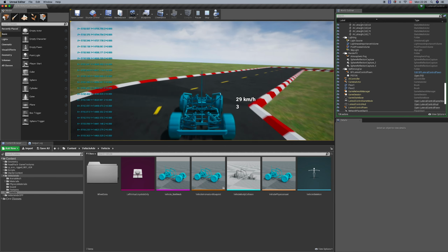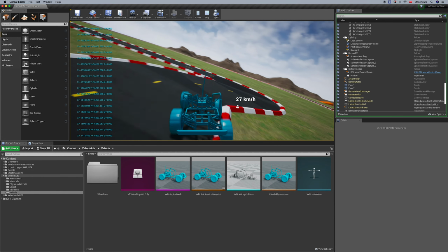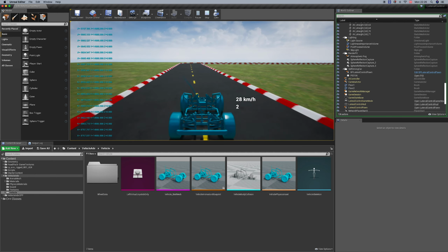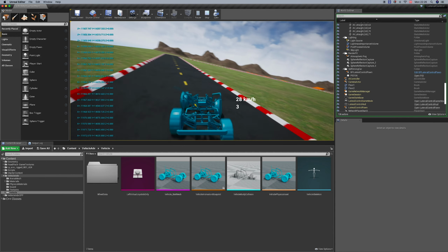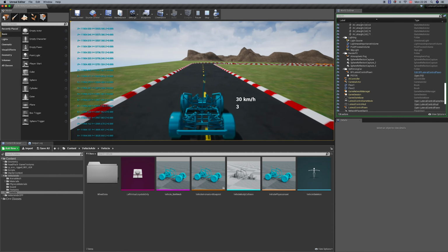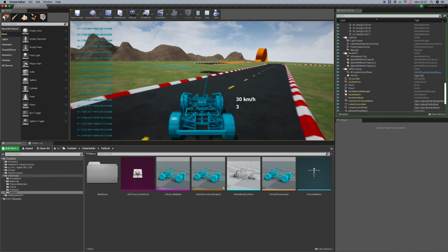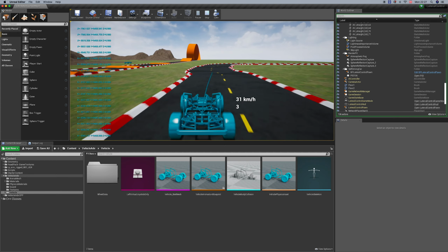These are the points on the spline. At this point, we will use them to estimate the head or look-ahead vector in the pure pursuit controller. So thank you, and in the next session, as I said, we will implement the pure pursuit controller using Unreal Game Engine.